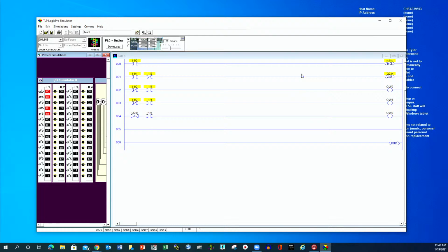See, it's true. My MCR is active. Why do you think it's jumping? You're disabling that whole zone. No, it is enabled because this line is true. Right, but when you make it not true. Oh wait, you know what I didn't do? No, but I'm actually jumping over. I'm completely jumping over all that stuff there, so it's not even scanning it. That's why it's not turning on. I just noticed I didn't add the other MCR fence. Yeah, I was going to say it's inside that block, right? So it's not going to change it off. Yeah, it's not even going to. Yes, you're exactly right.